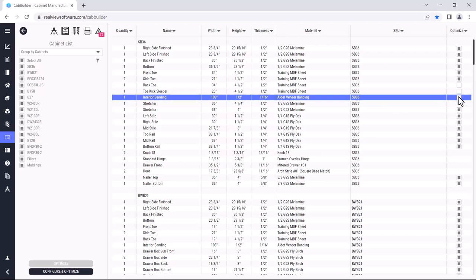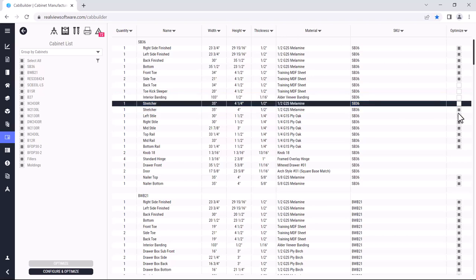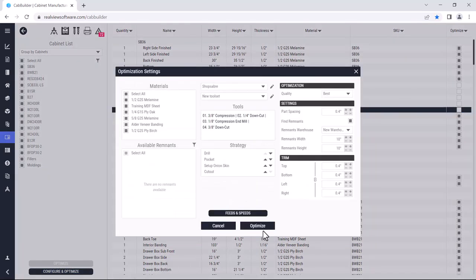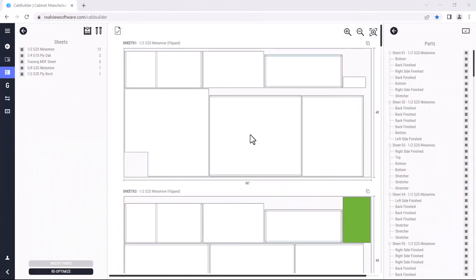The user selects which parts are to move to the machining phase and subsequently nest them. If they have applied a post-processor, the parts will have toolpaths and G-codes generated for the following module called Optimizer. This last module is where all the machining takes place. It is made of 4 sub-modules: Layout, G-code, Toolpaths, and Labels.